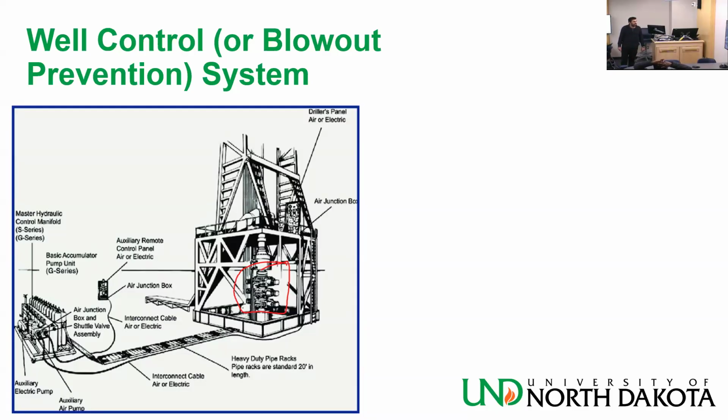It's very important. They are regularly tested. They follow protocol in the way they are tested and how often, the frequency at which they are tested. And like I said, there are several types of blowout preventers, of rams, and the operator decides on what configuration we have. Do you want 3 pipe rams and 1 shear ram? Do you want a blind ram and 2 shear rams and then a pipe?